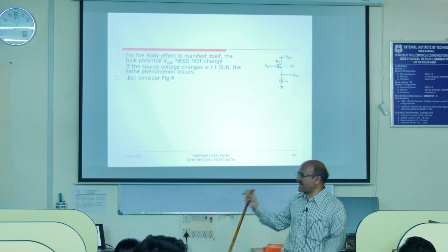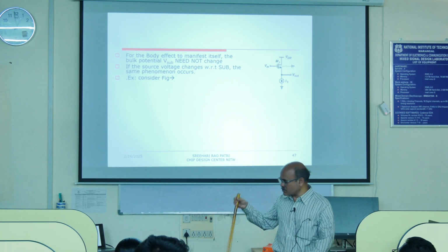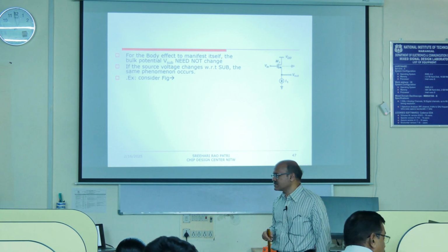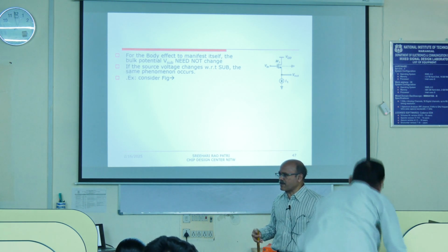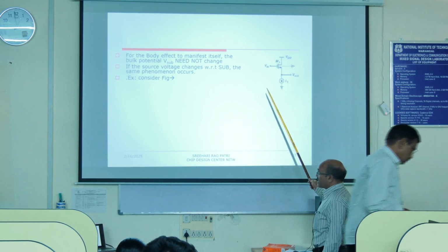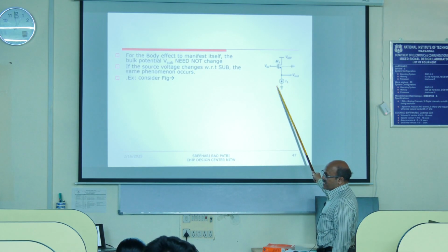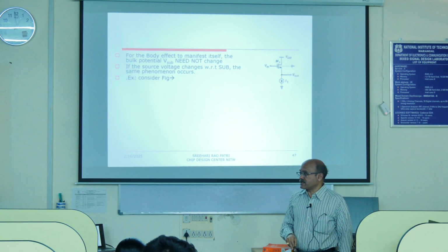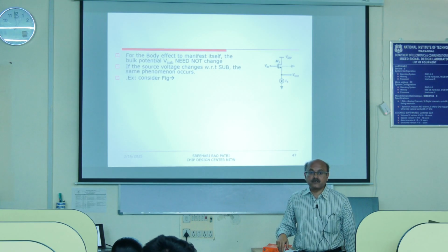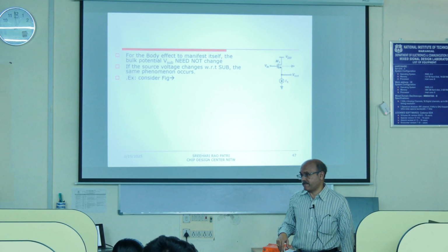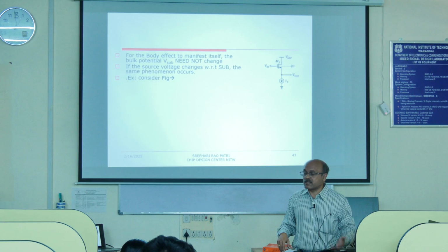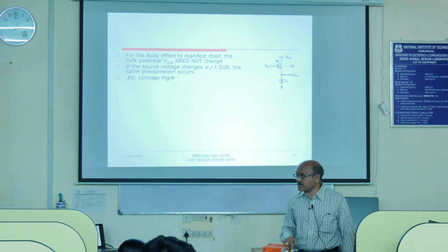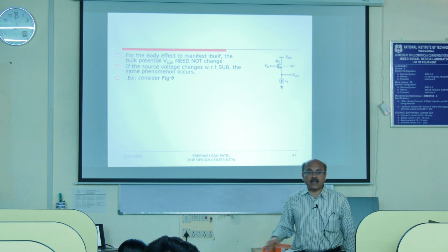For a transistor, when the gate voltage is above threshold voltage, the current should increase or not? Should increase, it's common sense. Current should increase. But what I have done, I have connected a current source here. So the fixed current is flowing there. It will not allow the current to increase beyond the fixed current. But from one end you want to increase the gate voltage, so current should increase, but you are not allowing it from the other end.